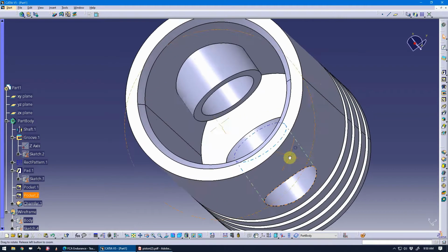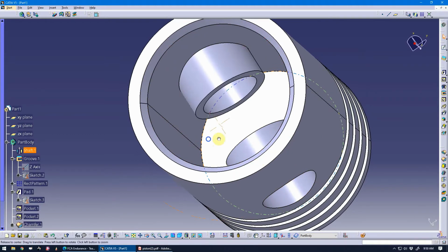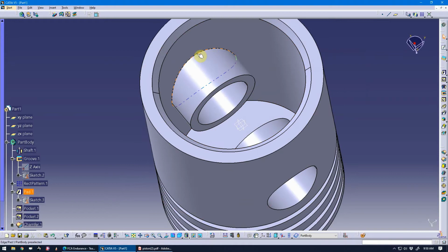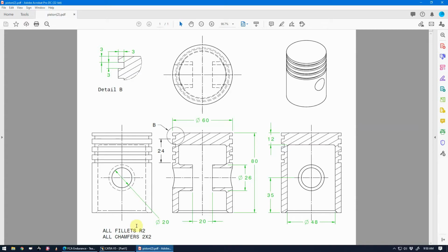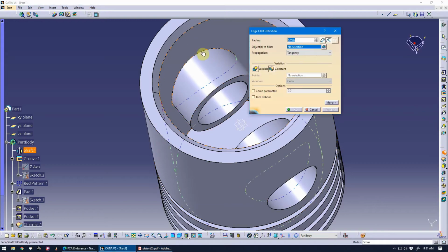And then fillets for the unfinished surfaces on the inside, which will be this bottom corner and around this edge of the boss. So let's do a radius of 2. So I've got a fillet. Make sure I do edge select. So I don't want to do a face select. So I'm just going to hover here briefly.